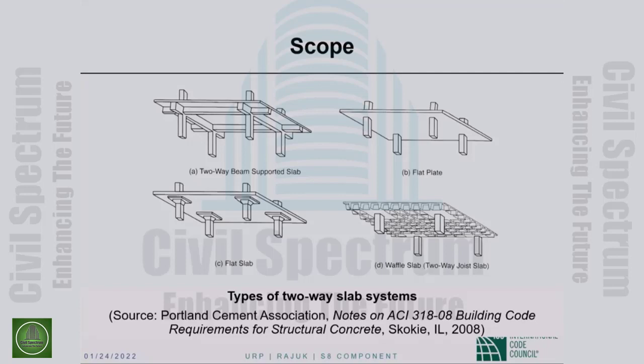The flat plate slab system will give us the shallowest story height, which you translate into a lot of savings in, first of all, cladding, secondly, electrical cables, HVAC ducts, telephone cables, anything that goes up a building. So that makes the flat plate, as I said, the most popular slab system there is in concrete.